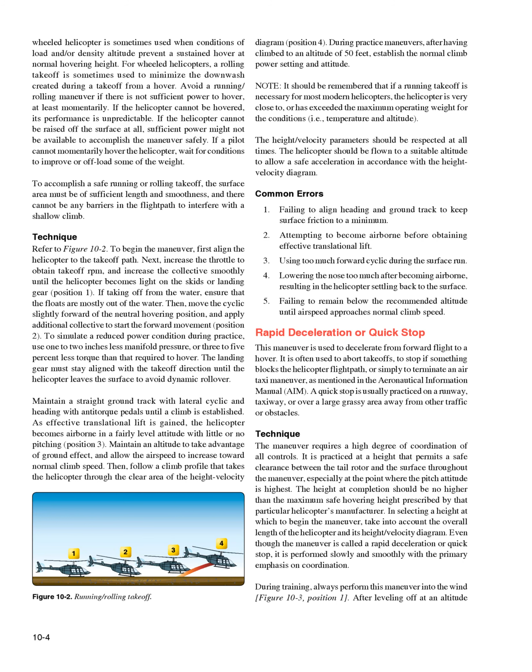Note, it should be remembered that if a running takeoff is necessary for most modern helicopters, the helicopter is very close to, or has exceeded, the maximum operating weight for the conditions, i.e., temperature and altitude. The height/velocity parameters should be respected at all times. The helicopter should be flown to a suitable altitude to allow a safe acceleration in accordance with the height-velocity diagram.